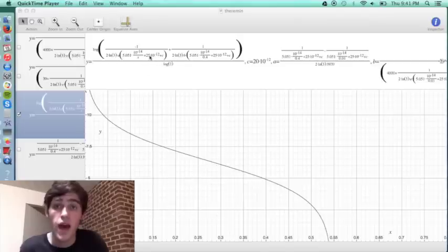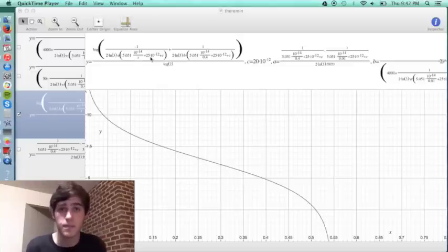And then within that is the expression for the capacitance, either the capacitance of the reference oscillator or the capacitance of the antenna itself. And if you look at the schematic for each oscillator, the antenna does not operate by itself.